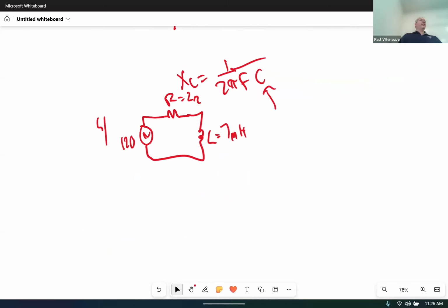What does the current have again? I forgot. Magnitude and angle. So I has to be equal to V divided by Z in this really basic, simple RL circuit. What's V? 128 at an angle of 0. We're going to pick it as a reference. What's Z equal to?